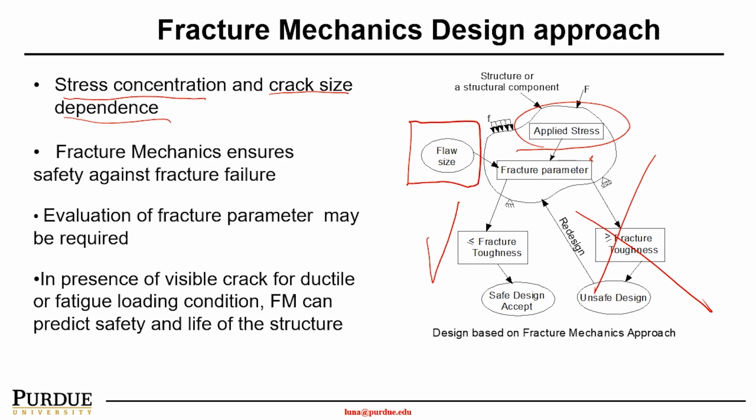So therefore, we want to use non-destructive testing, particularly when the material or structure is still in its service life, to understand the crack or flaw size. And as long as this size is smaller than the threshold, we're still safe. So the structure can still be in service.